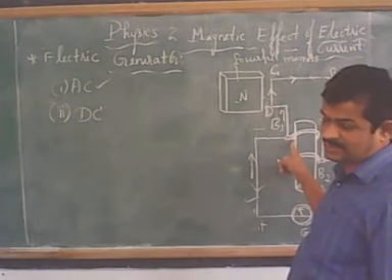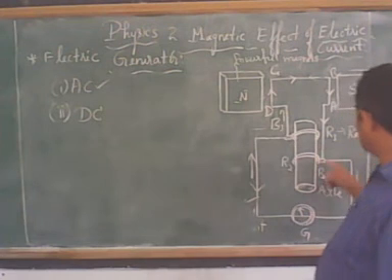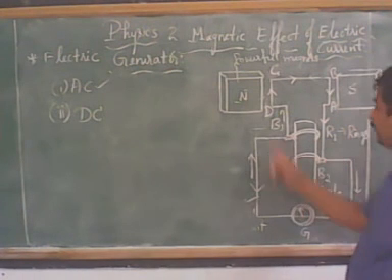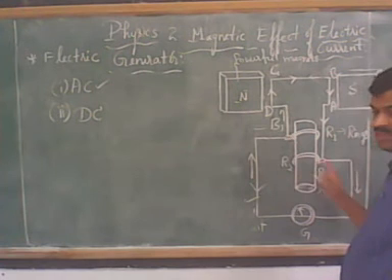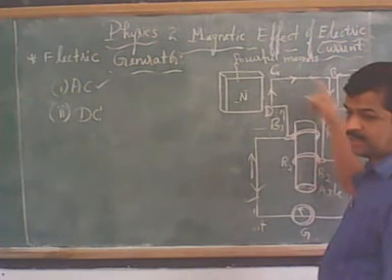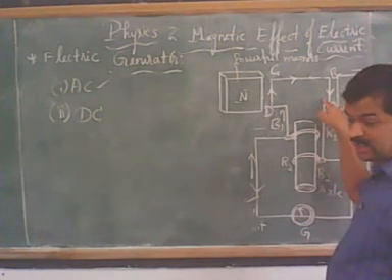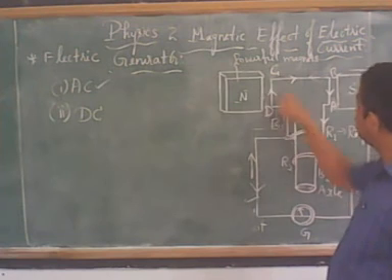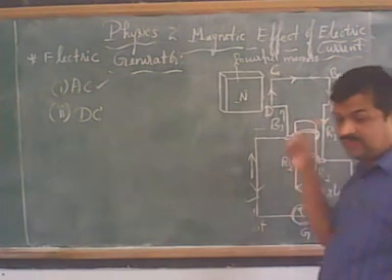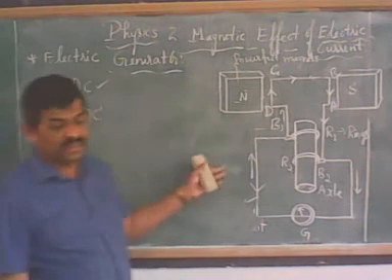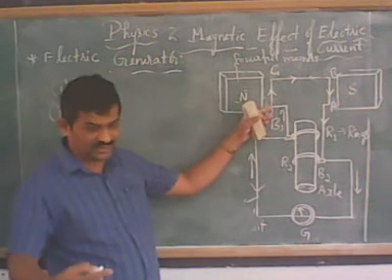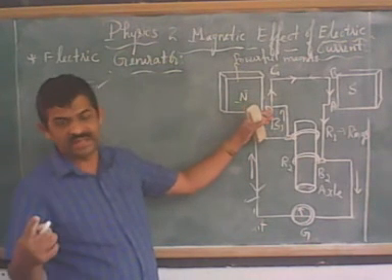In the first half cycle, the direction of generated current is B2 to B1, and in the second half cycle B1 to B2. In the first half cycle the current in the ABCD coil flows in direction ABCD, and in the second half cycle in direction DCBA. For every half cycle, the generated current in the coil in the magnetic field alternates, so it is known as alternating current.